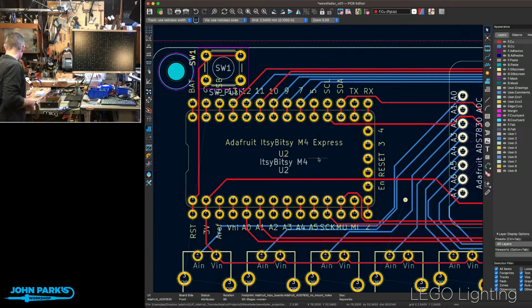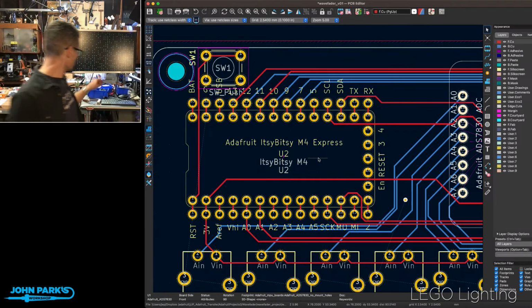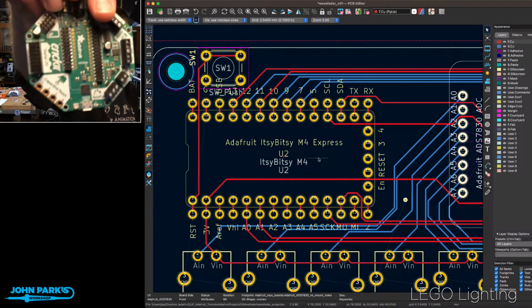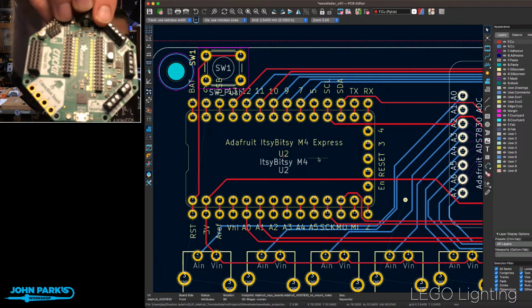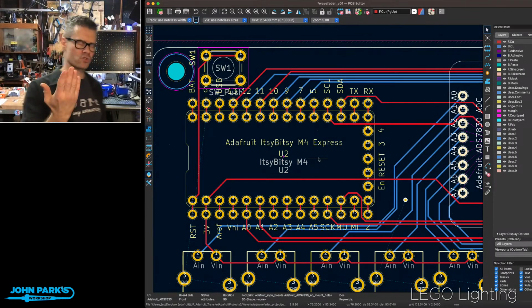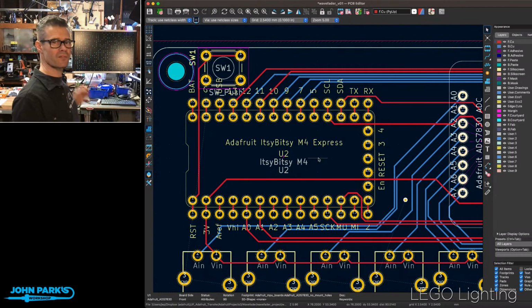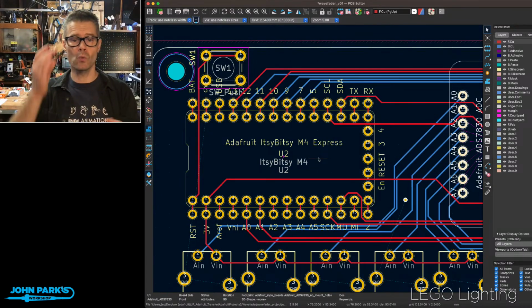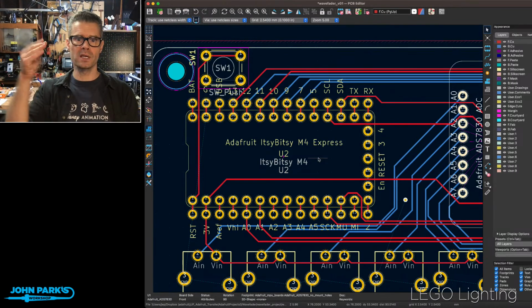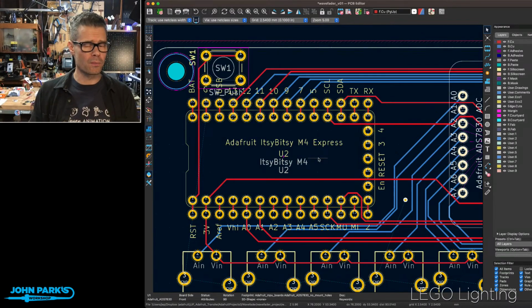Do I have anything like that right here? I thought I did, but I don't. Oh, here it is. Yeah, here's a cricket. So you can see there, right? Those are the normal feather headers, except they're double wide, and so that gives you an extra set of pins to plug stuff into. You could use headers if you want, and just put little cables into them with DuPont connectors, or even hookup wire will work. Or you could leave that free and solder onto there. You could solder the microcontroller on, or use a socket or header.